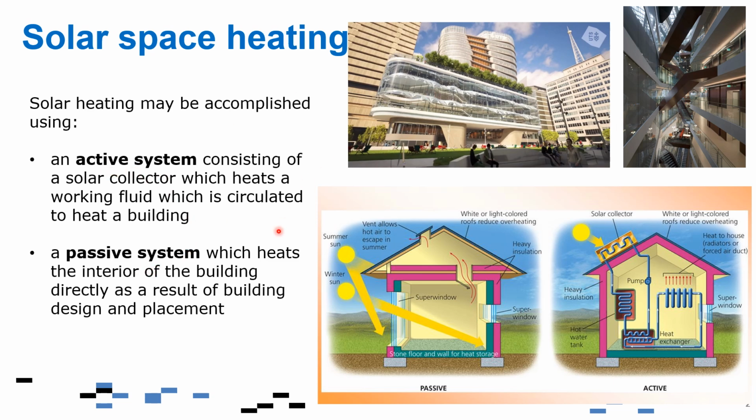The passive system basically means there are no moving parts. It's just the proper design of the houses or structures. If we refer to houses, for example, we can design the provision of glass in the houses, and also the roof toppings, to provide shading from the solar radiation.